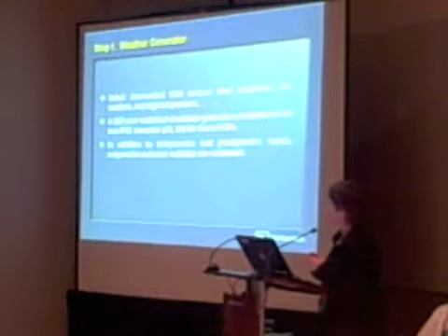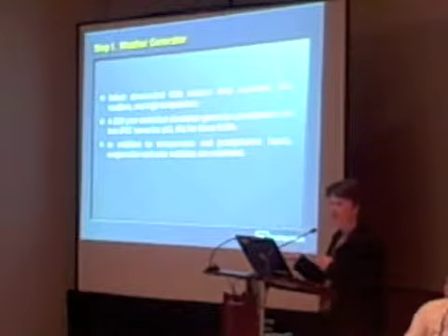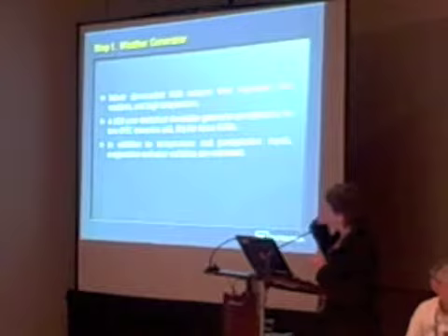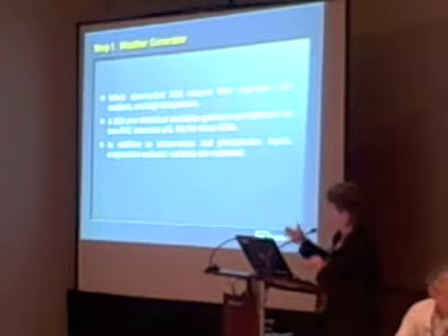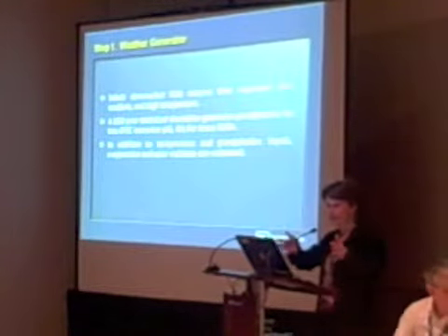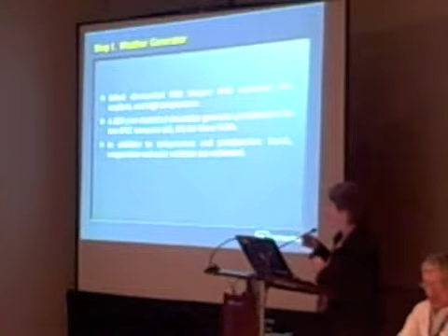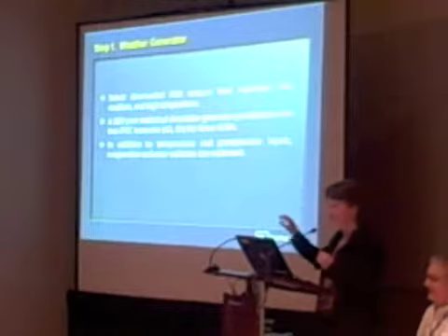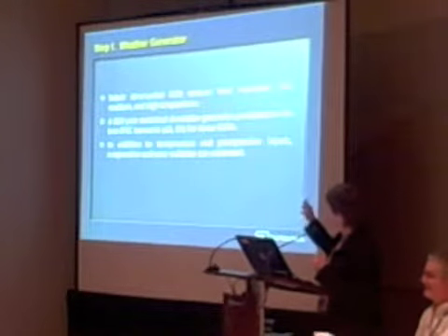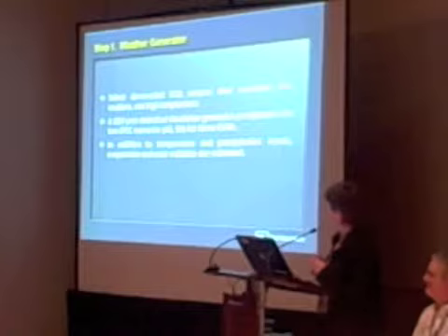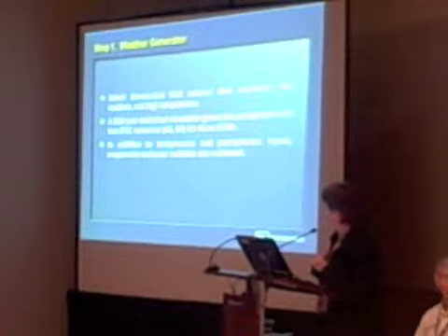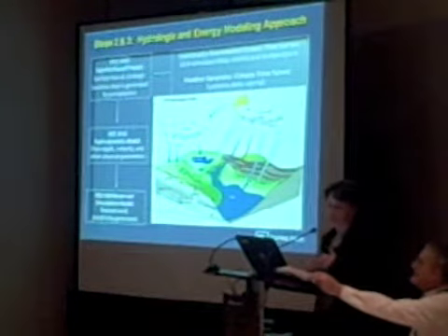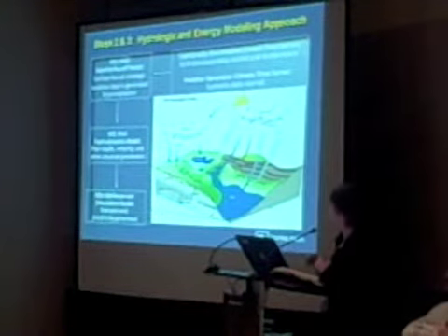That's what we've used here to supplement the temperature projections from the GCMs: calibrating the weather generator to observed historic data at the basin, and then using that calibrated data perturbed by the temperature data from the GCMs to generate essentially replacement precipitation inputs for the location. So that's projecting climate change for us for the next 100 years.